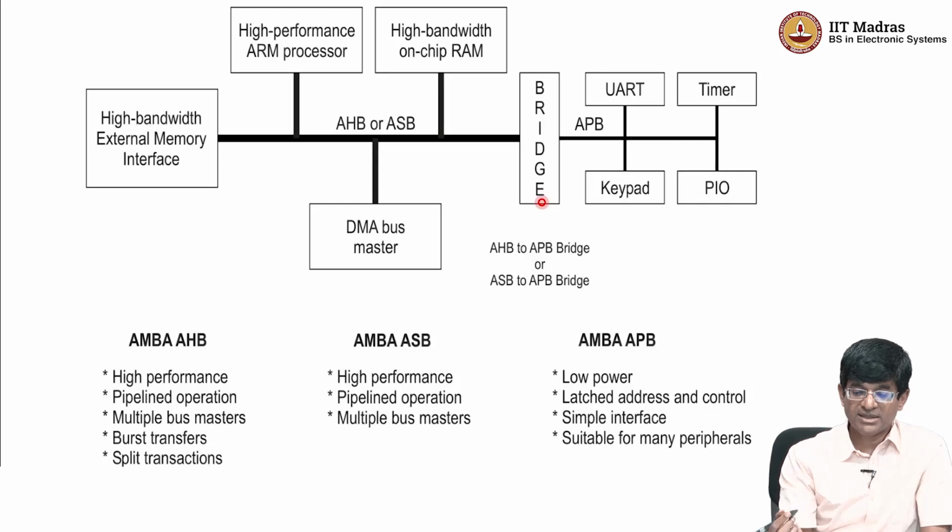Okay. So this is a very generic form of bus architecture. It is one of the most common buses for microcontroller based systems nowadays, primarily because ARM is the most common form of microcontroller that is available. And RISC-V also, most RISC-V systems also have some kind of support for the AMBA protocol, or to be more accurate, the more updated version, which is AXI, the Advanced Extensible Interface protocol, which is also from ARM.